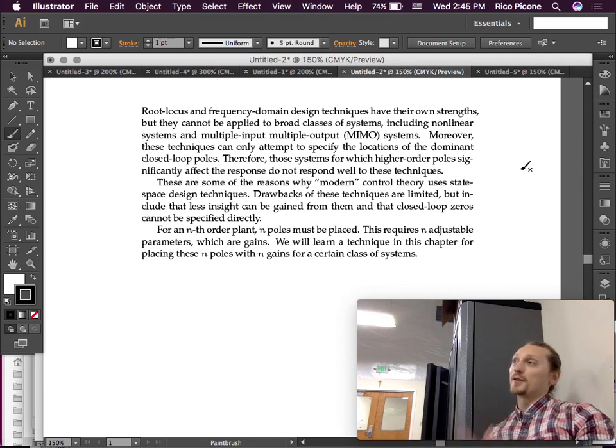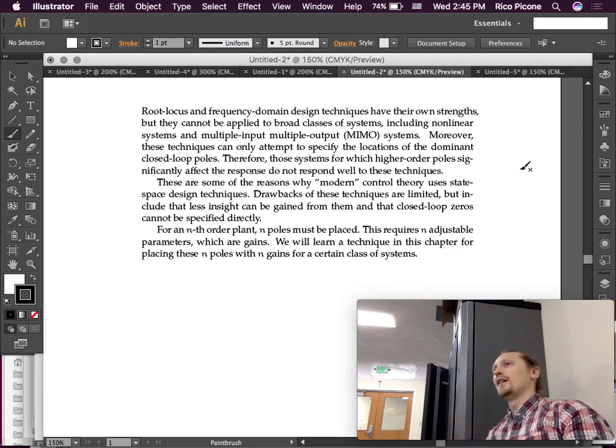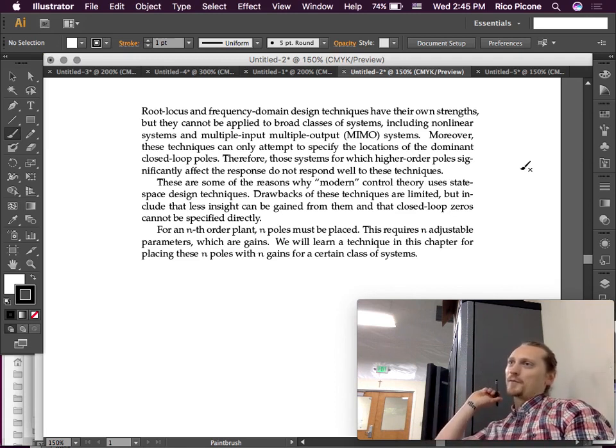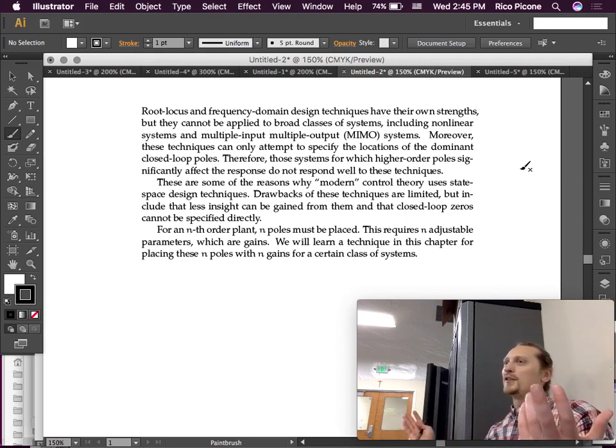And then from a differential equation, you can go to what is essentially a state space model, which is required for ODE45, which is a system of first order ODEs that are coupled, right? So if it's a 4th order single ODE, you can break that down into 4 coupled first order ODEs. That is something they talk about in the MATLAB documentation. You can look at it online. There's lots of stuff on that.